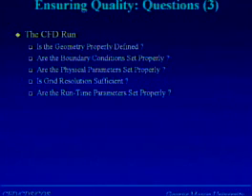So, the questions that we can ask here are, is the geometry properly defined? How accurate do I have to be in my geometry? Are the boundary conditions set properly? Well, particularly if you think about patient-specific modeling, this is a really big question. Are the physical parameters set properly? Again, try to do fluid structure interaction for patient-specific models. What is your elasticity model really? And what are the parameters that you're going to use for this particular patient? Is the grid resolution sufficient? Can you visualize the errors or estimate them properly? And are the runtime parameters set properly?